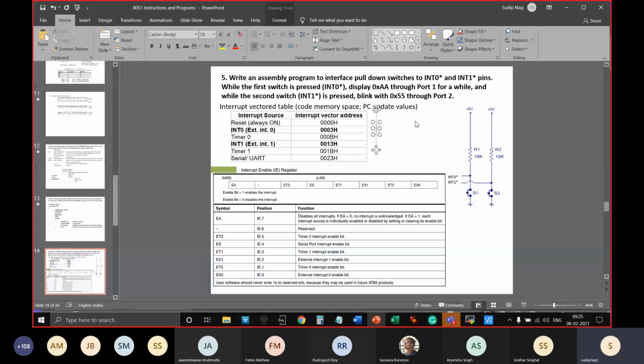But the other five variants should be initialized. They should be either enabled or disabled. The others are called maskable interrupts. The other five after reset are maskable interrupts. Maskable interrupt means I can turn it off, so it is not always on. It is on only when I need it.